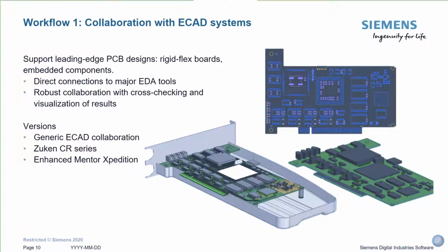But if you require, on the left at the bottom, a very detailed PCB representation in your CAD interface with all the details of the traces, the blind buried vias, the PCB stack, and the 3D geometry of the components within the enclosure, within the system, this is all possible. So you can really go between those 2 extremes per your requirement.